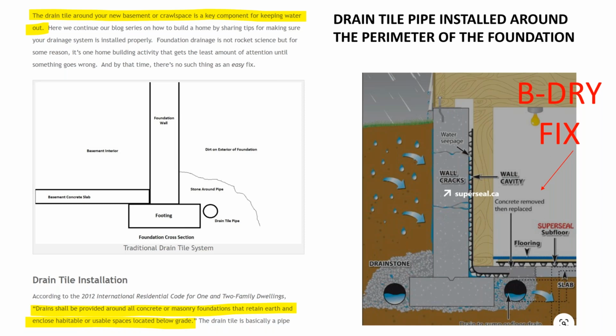My preferred way of waterproofing a house would be to seal the crack. And they have something that they use on runways. It's a flexible rubberized thing that they actually shoot into the crack, and it will expand and fill all the holes, which will alleviate the water from coming in through the foundation wall. That would be the preferable way to do it.